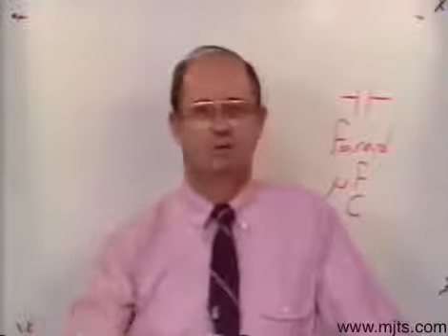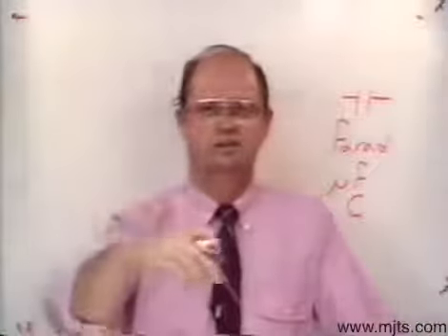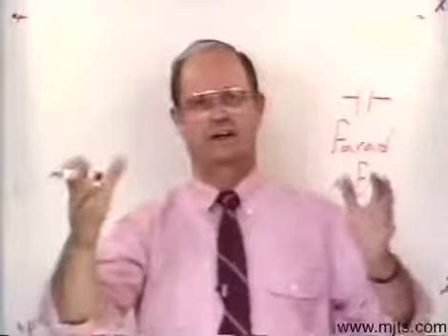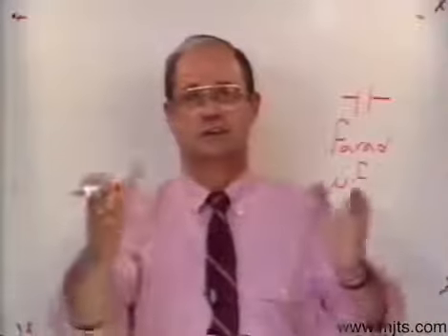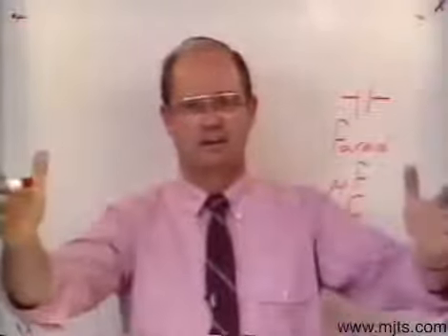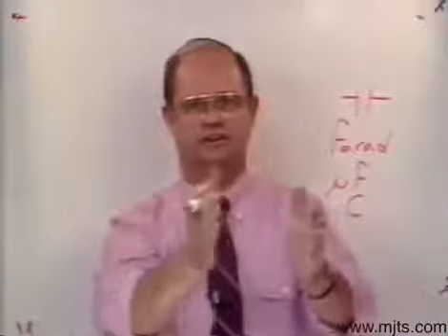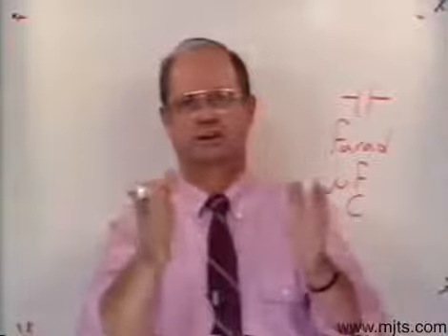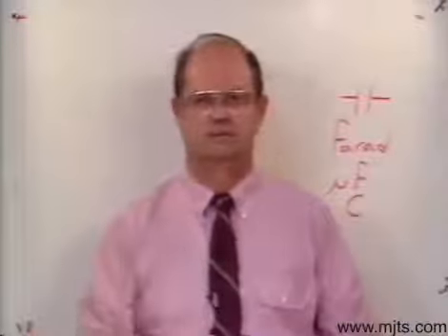Now, underground cable has a high capacitive effect in comparison to overhead lines. On overhead lines, you have a capacitive effect there. It's quite small. It can be large, but if I have my conductors closer together, and of course there's air as a dielectric material, they're going to give me more of a capacitive effect than if I had them spread out further.